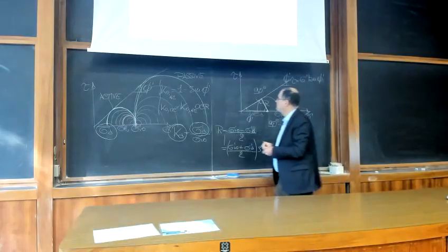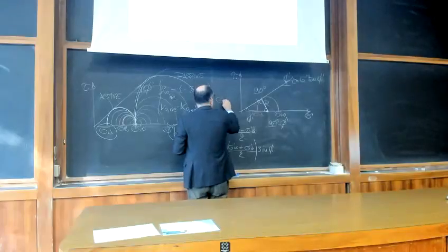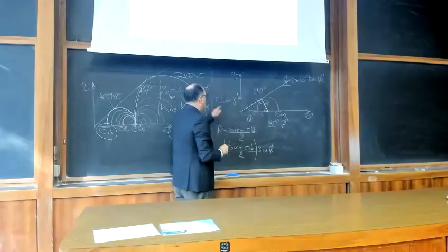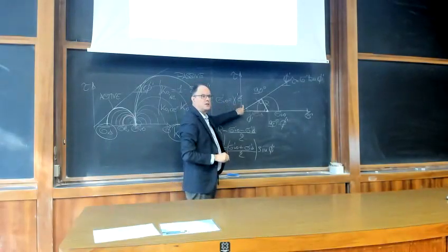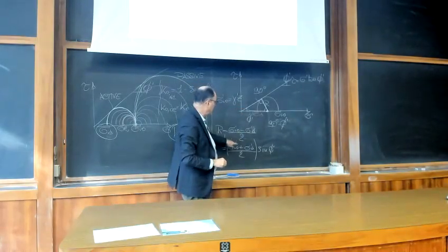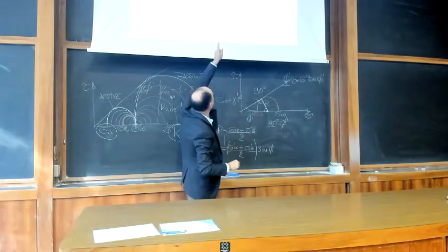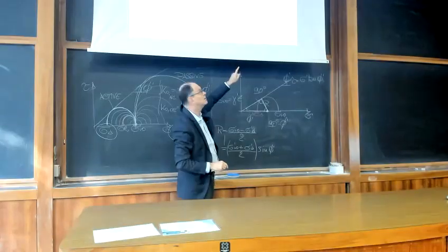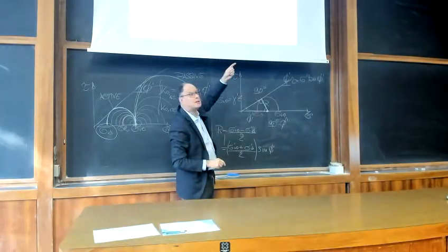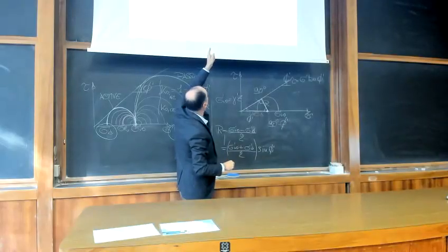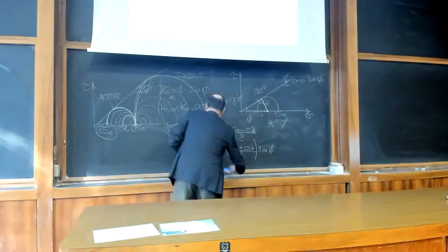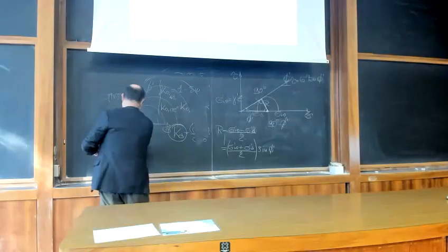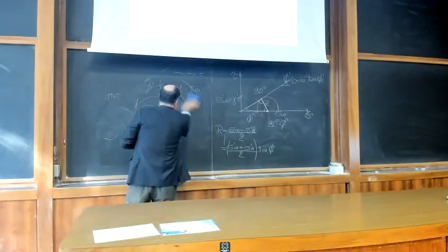And remember, sigma v naught is, for example, gamma dash z, so it is linearly increasing with z. In the same way, the horizontal sigma a is linearly increasing with z, times a coefficient which is 1 minus sine phi. Let's put it here, otherwise it's too difficult to read on the slide.